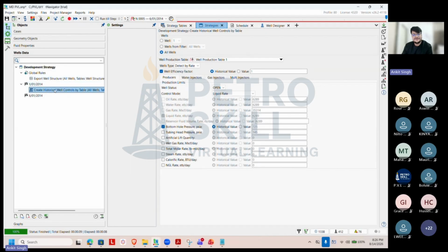Now that we have added a constraint, what this create historical well control means is that you are telling the simulator, this is my history data, and I want you to simulate the fluid similar to what I have in history.